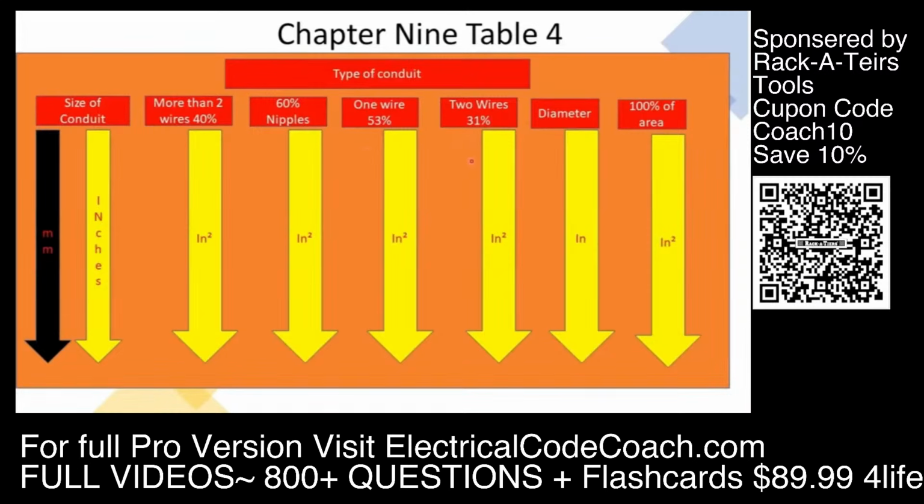And the same thing with 2 wires. It would be if you had only 2 wires, or if you had 2 cables in the conduit. Or if you had 3 cables, like 3 pieces of Romex, you would use the 40%.